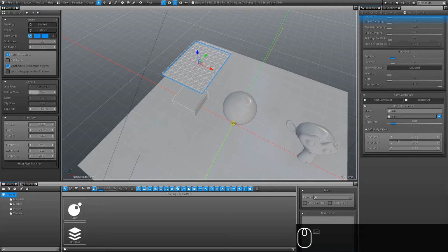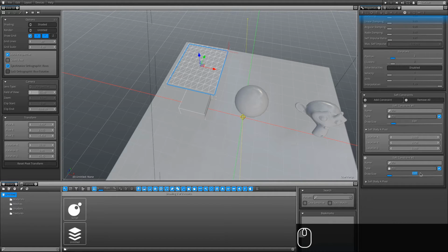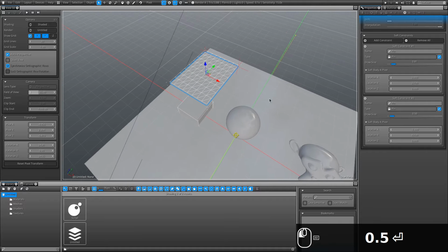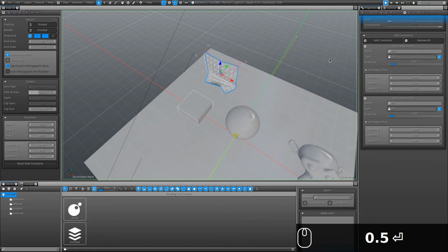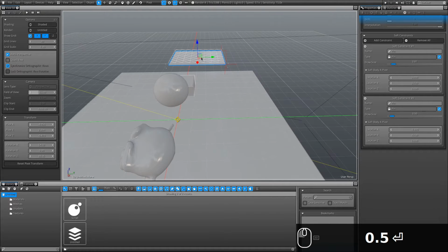So what I'm going to do, I'm going to use the slider here, and it doesn't matter even if we go overboard, it would snap automatically to the closest node. And I am going to place it here. I'm going to create a second one. Same thing. Get a better visualization. Drag it over a bit more, and I am ready to have another test run. If I hold shift and play, we can see that now we have our cloth that it's hang over here.